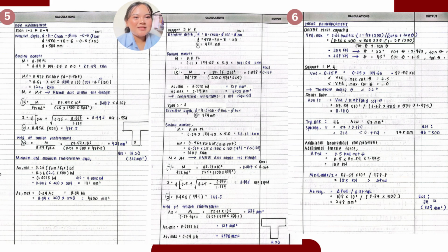With the bending moment, we proceed to design the main longitudinal reinforcement. We analyze both the midspans and the supports. For example, looking at the midspans, we calculate the effective depth and check the K value against K bar to verify that compression reinforcement is not required. We confirm that the neutral axis falls within the flange, which simplifies our lever arm calculation based on the required area of steel As. We select suitable high yield bars like the 1H20 bars provided, ensuring that the area provided falls between the minimum and maximum allowable limits.